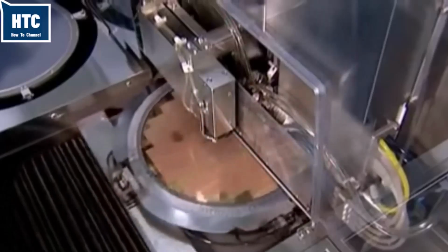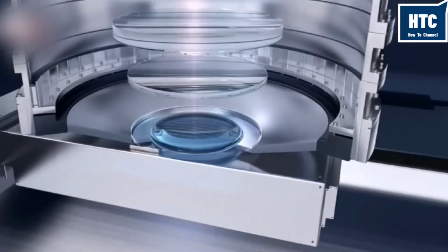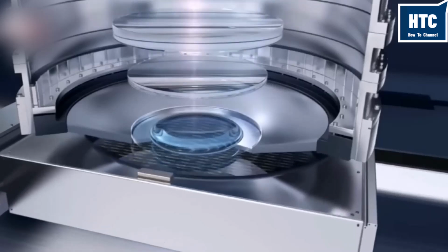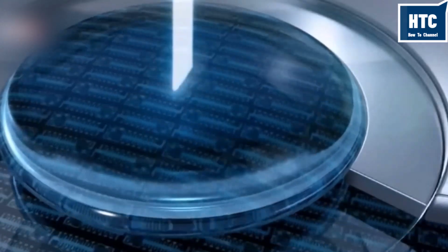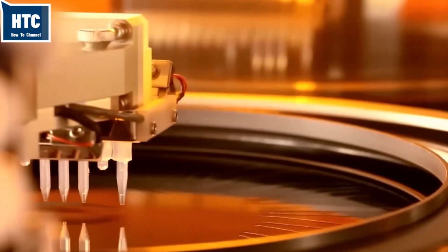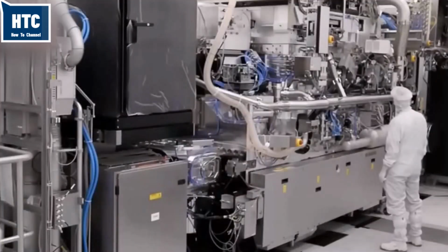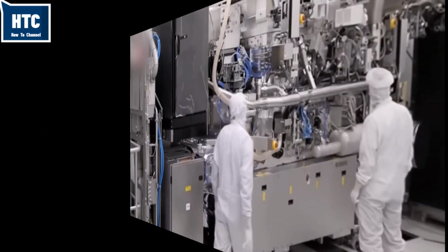However, copper kills silicon. If copper atoms touch the silicon transistors, they migrate into the material and destroy its function. To prevent this, a microscopic barrier layer of tantalum or tantalum nitride is applied first to line the trenches. Then, using a process called electroplating, the wafer is dipped into a copper sulfate solution. An electrical charge draws copper ions onto the wafer, filling the trenches and vias.